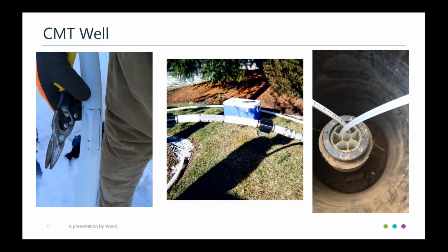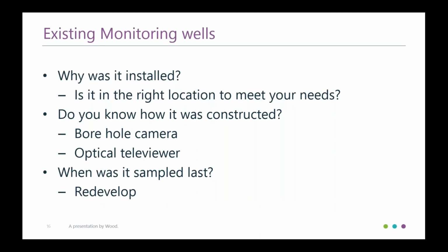If you have existing monitoring wells, you really need to start thinking about some things before you use it. Again, why was it installed? Is it in the right location to meet your needs? Do you know how it was constructed? So just because it's in the right location, if you don't know how it was constructed, where that well screen is, it may not meet your needs.